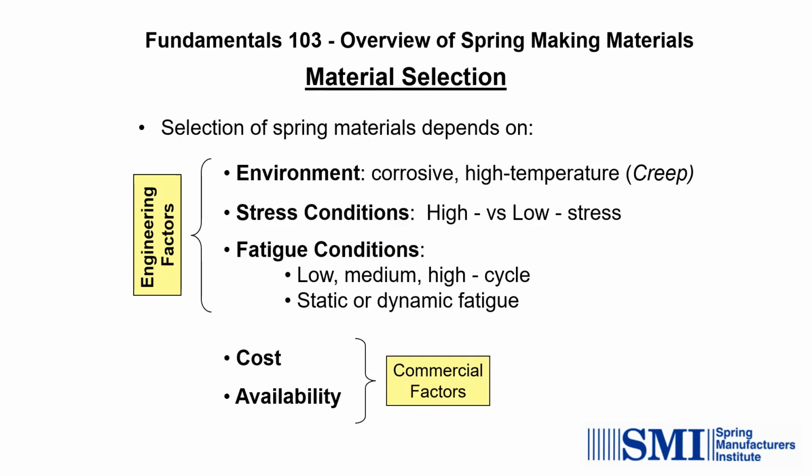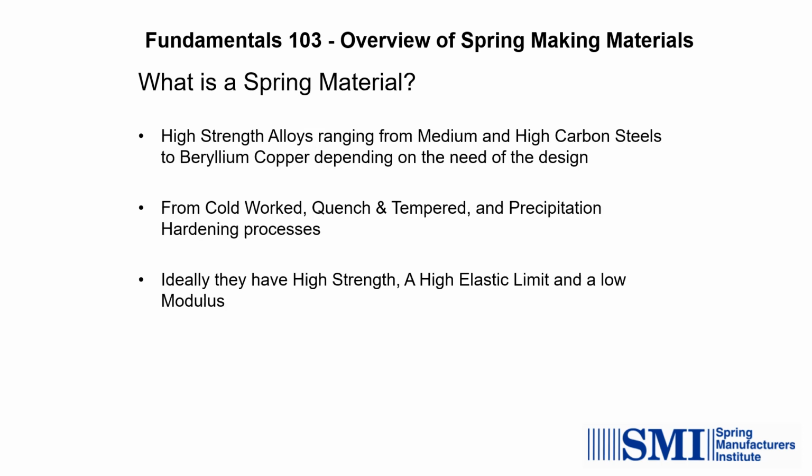With regard to material selection, engineering factors such as the operating environment, stress conditions, fatigue conditions. Is the spring being used in a static or dynamic condition? What do I mean by that? For a static condition, think of your hot water tank. The pressure relief valve will sit there for years and may only operate once in its lifetime. For a dynamic condition, think of your car's engine. You need the engine valve springs to cycle billions of times. There are also commercial factors to consider when selecting a material, such as cost and availability.